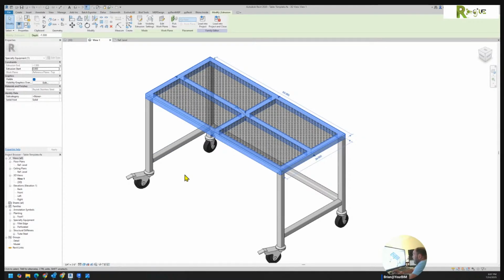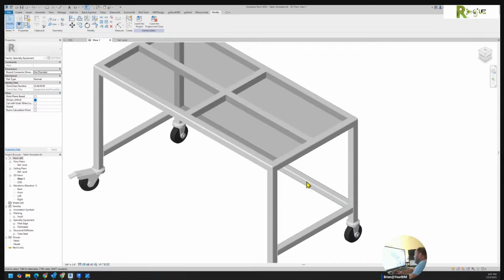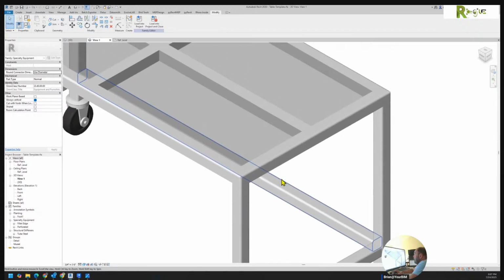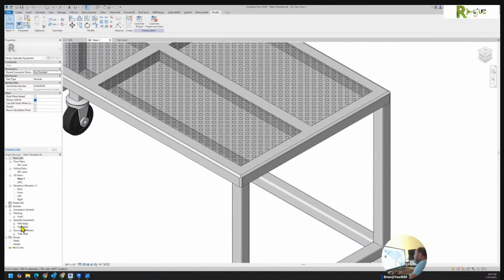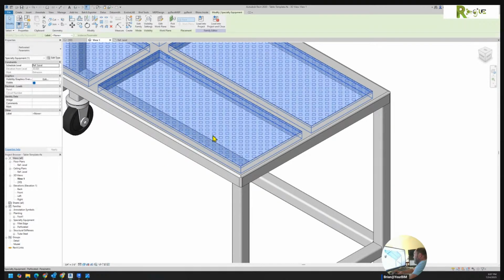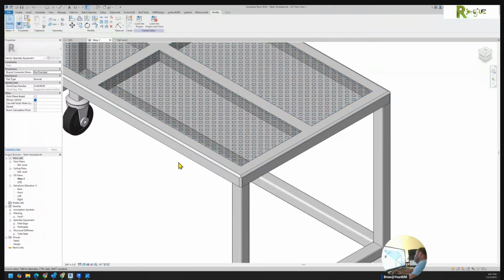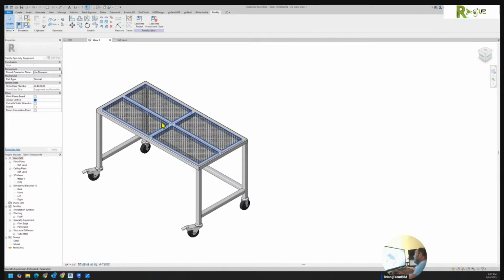And then what we do is we're going to hit that thing with a lot of different face-based families. So you see the one for the perforated edge, right? It cuts a hole and fills it back in with another object with material. Trust me, I had played with the idea of splitting that face and painting that face. This worked so much better.